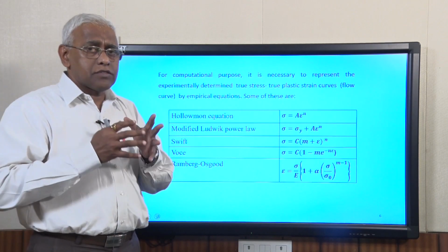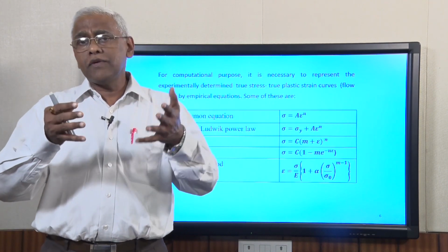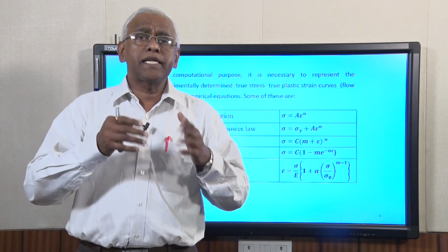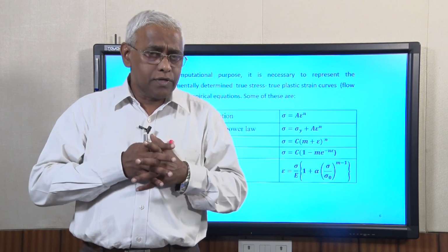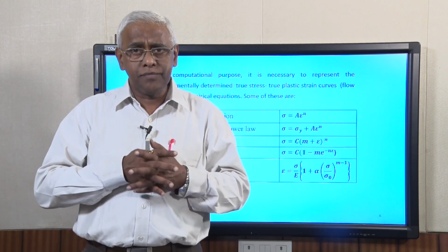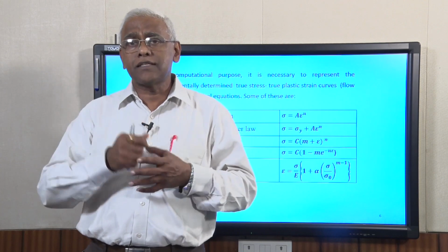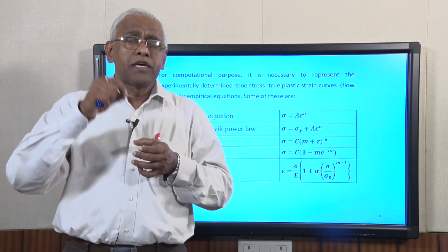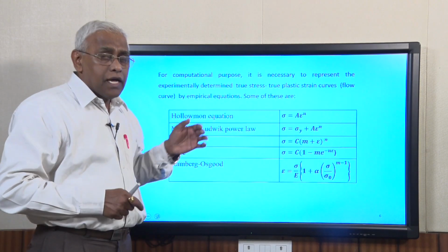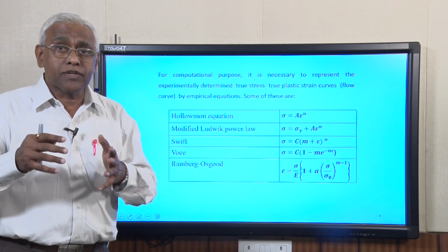In the normal case, you take the material, which you might have got from the market or purchased locally, and you do a full annealing, so that the material becomes soft. There is no effect of strain hardening and the dislocation densities inside the material are minimum. In that very soft condition you carry out a tensile test. So, you get the exact representation of the stress versus strain plot from the data, and this data will be used for further plastic deformation studies for analysis purposes.